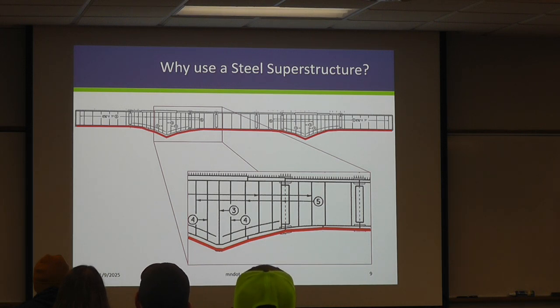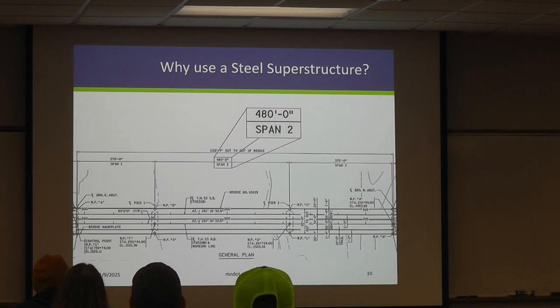Shallower sections. So we have these 2 points right here. Oftentimes the most force that your beams need to carry in a continuous span, and we'll talk about this in a moment, is right over a substructure. So in this case, we can use more depth right up here and less depth in the span, which could have an advantage if you're trying to go over a roadway, right, meet your vertical clearance requirements. So steel is highly adaptable to these types of things where you can put the most material where you need it. We also can do very long spans.